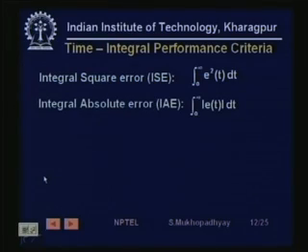So if the error magnitude goes double, then the control performance criterion which is to be minimized goes 4 times up. If you go 3 times, it will go 9 times up, which means that we are heavily penalizing large errors. So when we want to heavily penalize large errors, we generally choose powers of E, and square is chosen because the square criteria generally leads to very nice solution equations, because by differentiating square you get linear equations which are very easy to solve.